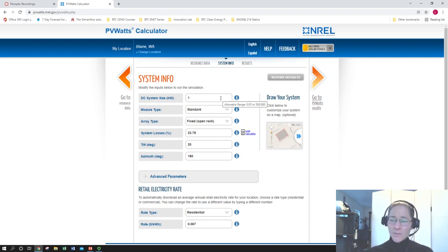Now, obviously, if we're talking about battery storage, the idea of the inverter is a little bit, why are we even using an inverter? Yes, in this case, we probably wouldn't even have the inverter. The PVWatts system info assumes you're using an inverter, very likely because this particular program was built up around mainly grid direct demand. But if we put in an inverter and we make some assumptions that it's running very efficiently, we will at the very least be giving ourselves a conservative estimate of what kind of generation capability we would have.